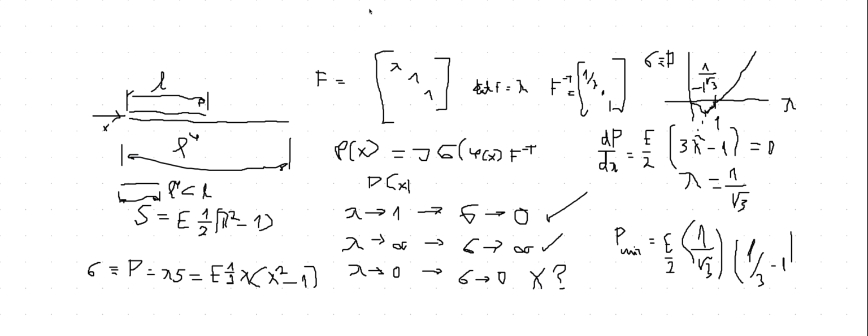So why was that? Well, because when you have plates and shells, you have large displacement, large rotation, but very small strains. So you end up having only this type of region to use, either small compressive or small tensile strain, and then basically you are still fine because Saint Venant-Kirchhoff material would stay in the neighborhood of the linear type of constitutive model, and you can handle the large displacement, large rotation properly with the Green-Lagrange strain. But if you had an application where you had to have a very large compressive strain for any reason that you want to study, please know that this type of material is not going to be the proper way of doing it.